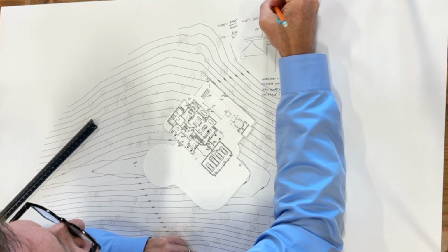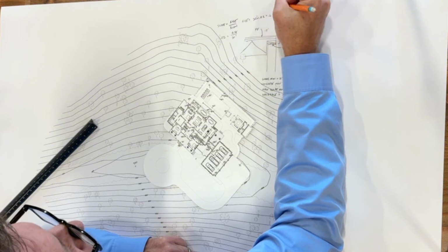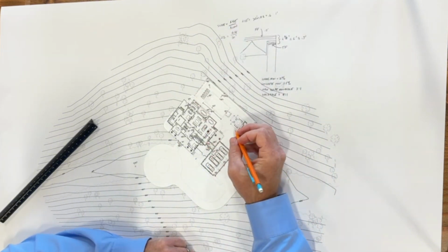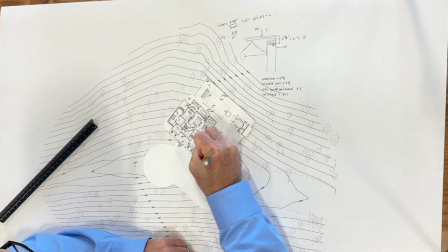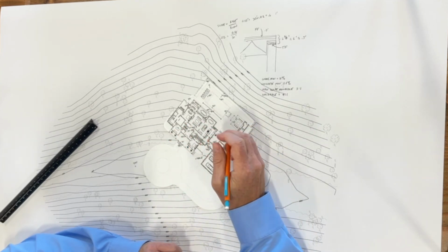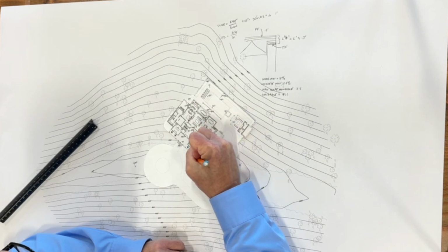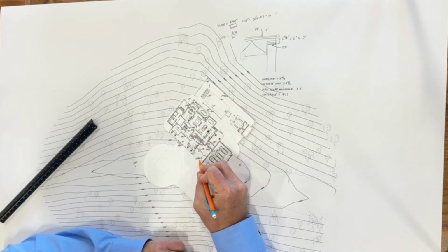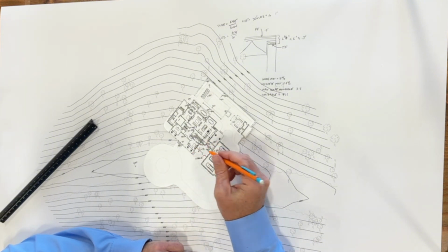0.6, so that's really at least 6 inches. So what we'll do is we'll just make this a foot drop just to make it dang sure the water gets out of there. So that means that point right there has to be a 940.5, right? I didn't go short, I went more to make sure it gets out, so that the water here is greater than a 2% slope. So that spot has to be that or lower, or water will get stuck in this courtyard, right?